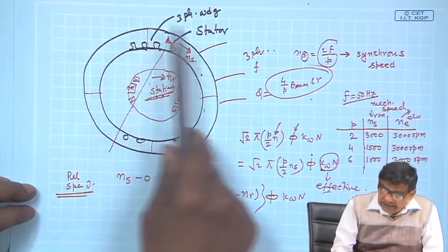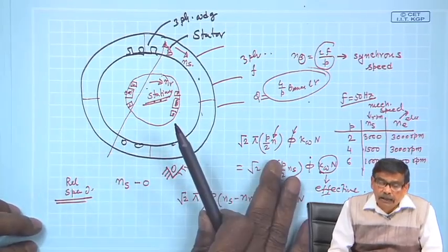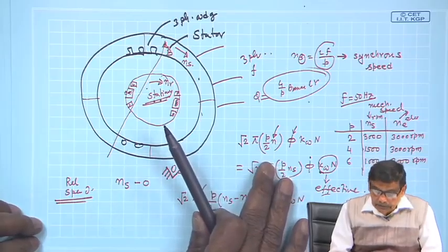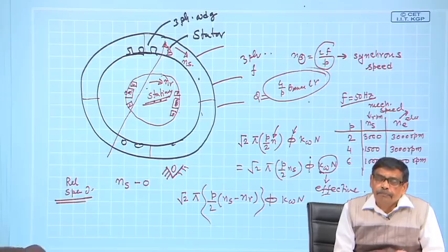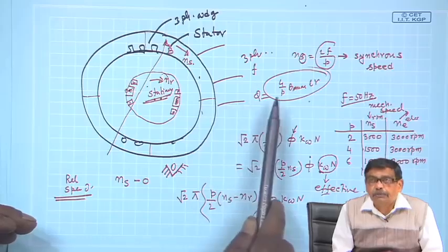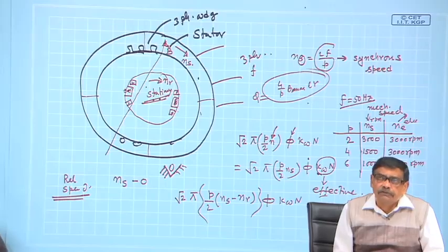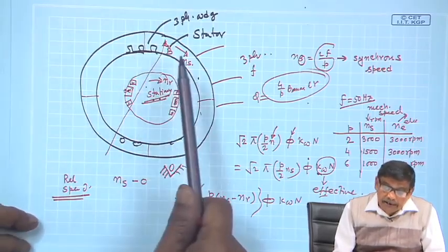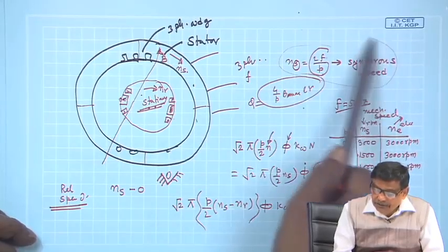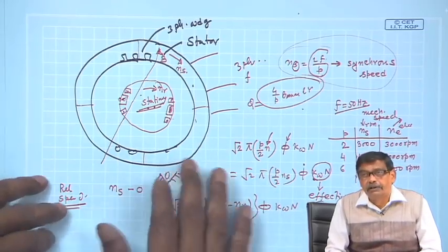Therefore, these are the things you please go through very carefully, and always remember, while specifying the speed of a rotating magnetic field, it is a good practice to always write down, okay, this is with respect to this fellow or that. In general, the speed of the rotating field depends upon the supply frequency, which is 2f by p, and it is with respect to the structure which houses the winding. Thank you so much. This is an important lecture. Please go through it.